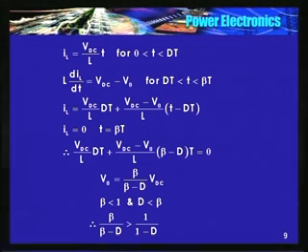Okay. So if beta is 1, that implies that current is just continuous. We still have the same expression, which is for an ideal boost. V0 is equal to VDC divided by 1 minus d. Current is at the boundary, in the sense current just touches 0 prior to closing S. Okay.